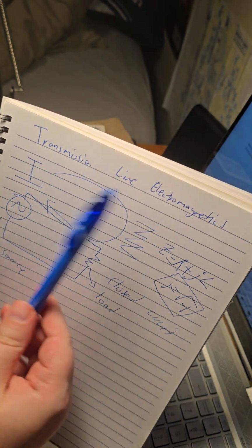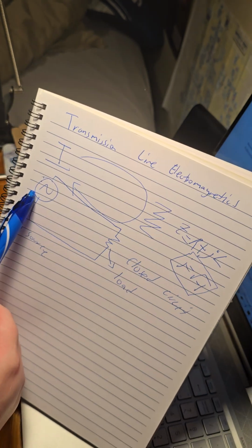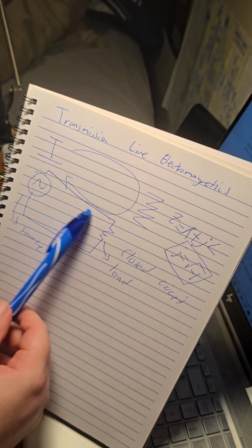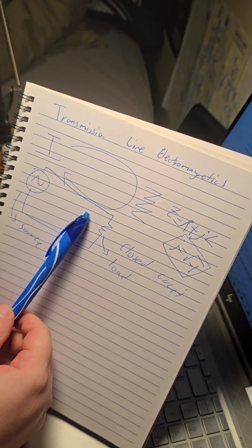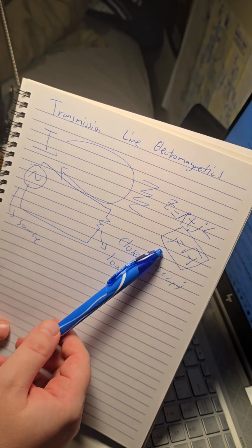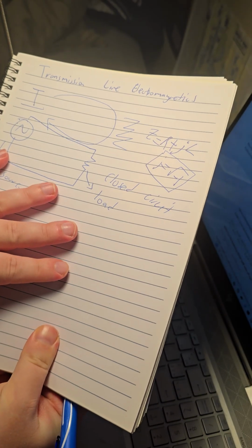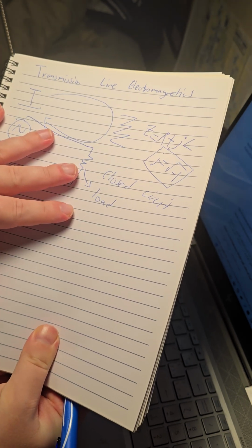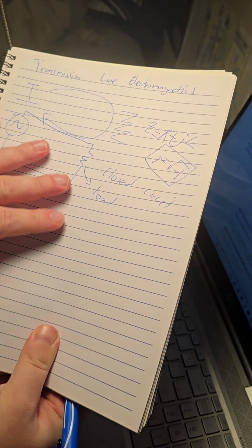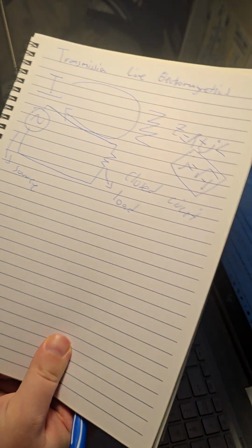Now, what is transmission line electromagnetics? When this wave is so small that it changes with the length of this circuit, or when this circuit is so big that this wave still changes with the length of the circuit, then things don't behave linearly in steady state. Or we do have a steady state in the end, but it's always changing with time and distance. And then we have transmission line principles and effects.